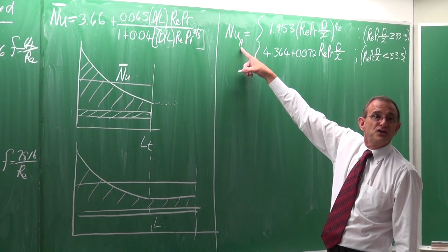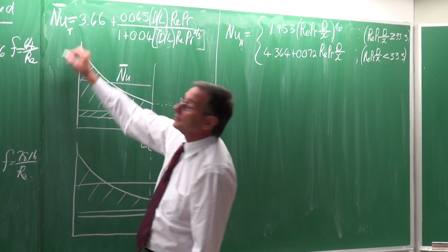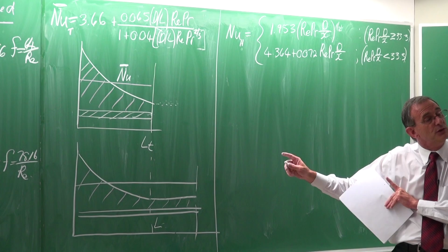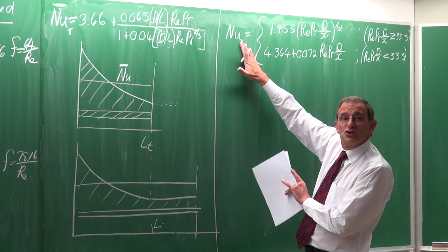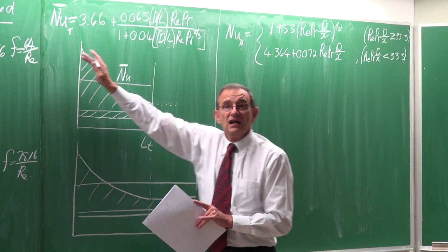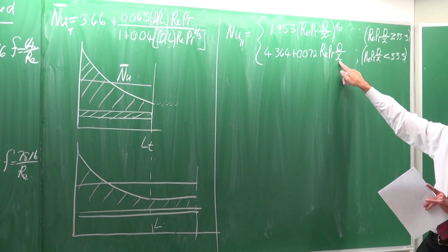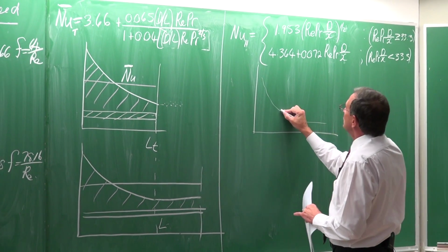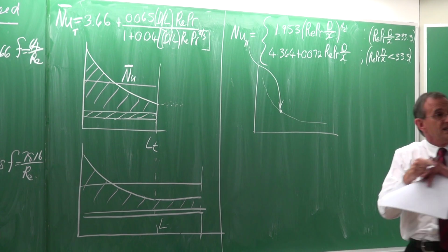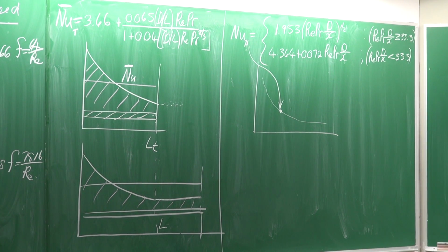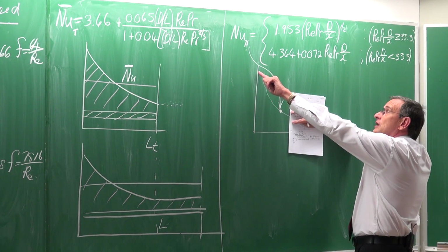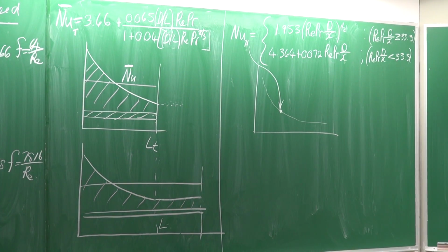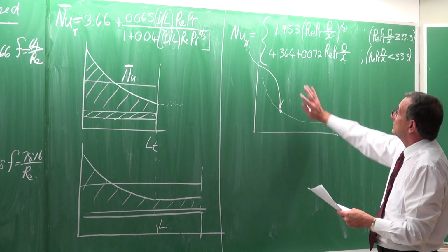Therefore, take note, I'm putting in the h there, and let's put in the t there in that equation, so that we can distinguish them from each other. There's a very important difference between these two equations, except for the fact that this is for constant heat flux and that is for constant wall temperature. The difference is, here we work with x. So in this case, in terms of the developing part, it would give you a local value at one specific point. It doesn't give you the average over a length. So if this is the length of your tube, you will have to calculate it from 0 to L, and then integrate it to get the average over the length. So the equation is not that friendly, but at least there is an equation.